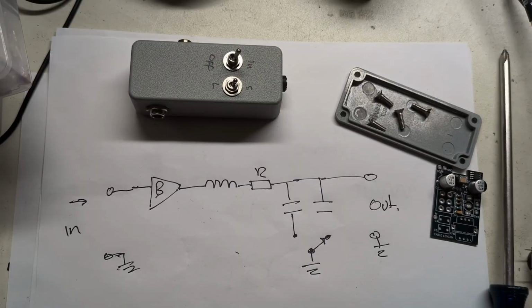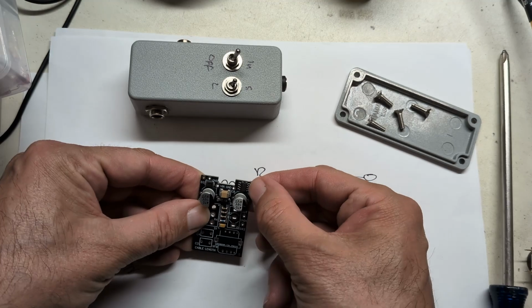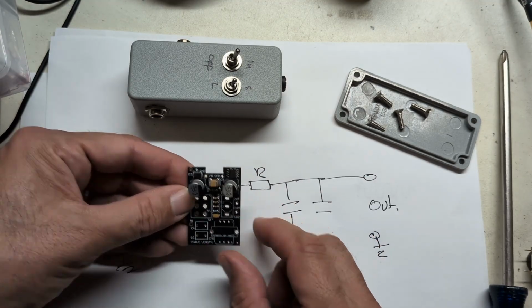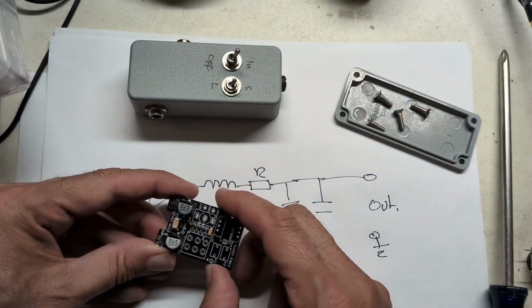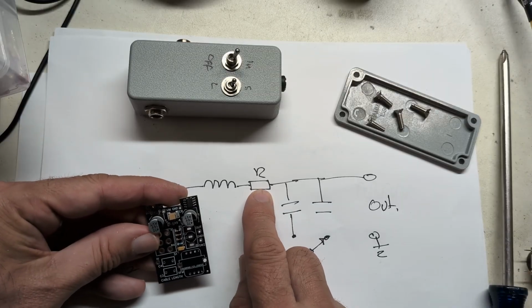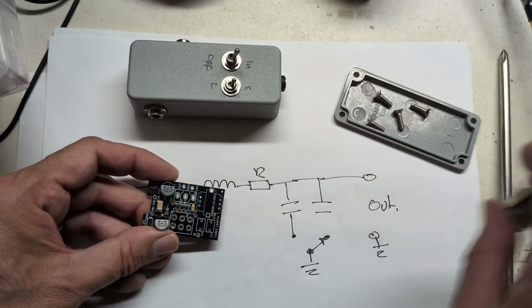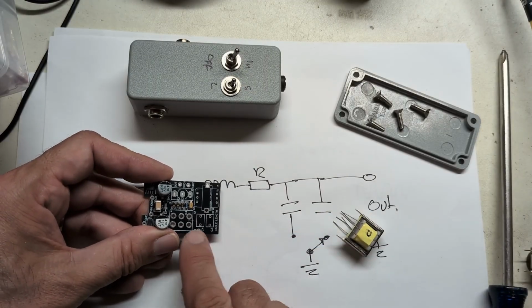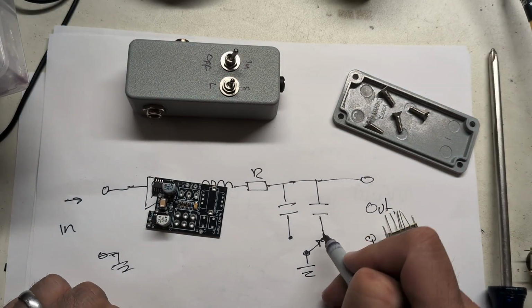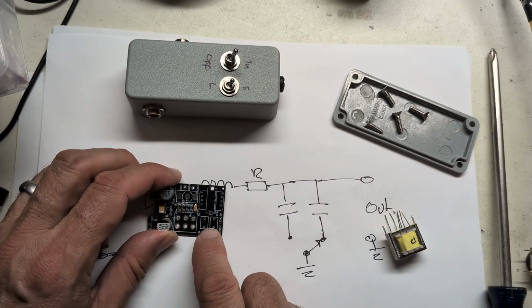And so I had some boards built. This is one in its raw form. So this is power supply filtering. There's the buffer there, and then these are the resistors that either set up the 4.5 volts that we need to bias this guy, and also the resistance value here. And then what I did in the design, and this is where you would place the transformer, and then I didn't do these 2 capacitors as a surface mount. I did them so people can change them, because this is how we're going to move the curve around